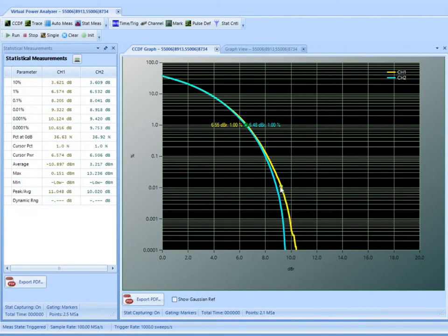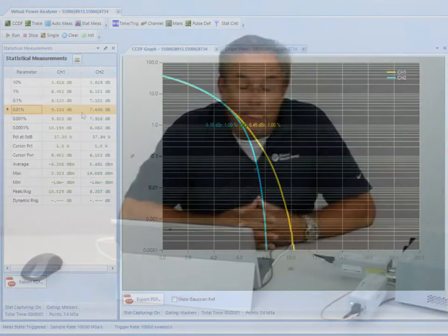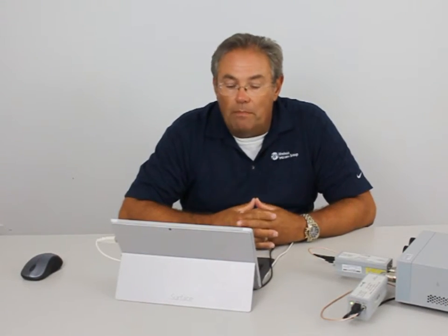place. And as we're going to see in these lower percentages, the separation is occurring. And what we're looking at here in our chart is that our average power basically stays about a 14 dB gain, but what we're noticing is at various points, especially here, we're starting to see a 1 dB separation already at 0.01%. This is affirming that we're seeing compression take place of these peak to average signals. Crest factor is a very important measurement.